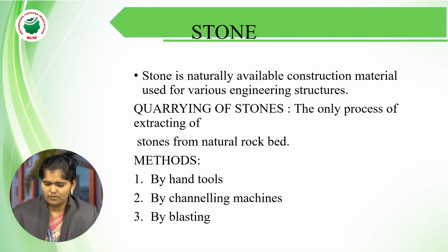So here, first thing, quarrying of stones. What is quarrying of stones? The process of extracting stones from the natural rock bed is called quarrying of stones. We use three methods for extracting the stone: by hand tools, by channelizing machines, and by blasting. In the hand tools method, we use only hand tools, and channelizing machines means machines are used in this method.